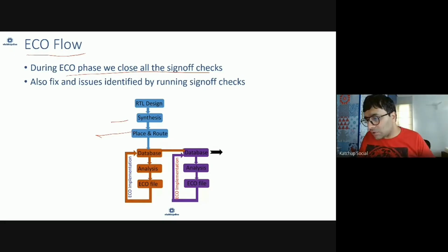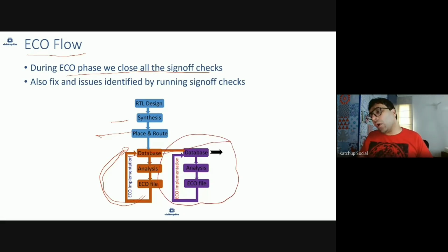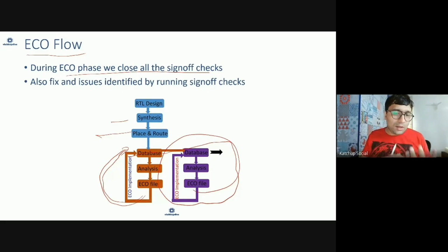When you fix issues, tools allow you to make small changes. Let's say you found a timing issue. STA tools allow you to do ECO changes, where a small change will be made to meet timing. But if you make any change, you have to do all the verification again. You will have to maybe run the gate level netlist again, verification again, maybe run timing analysis again. All those things need to be done again. Always make sure the chip works correctly.